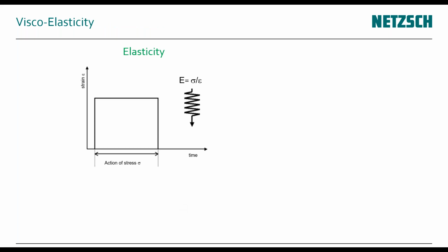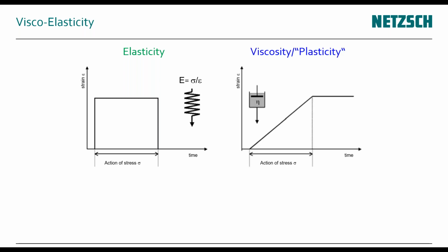So what is that viscoelasticity? We can think of a polymer being made up of elastic parts. So they're like spring-like parts you can see here on the right. What happens with the elastic part: you excite a sample, so you apply a stress upon your sample. And once you do that, there will be an instantaneous strain. It just stays like this. If you take away the stress after a while, the strain will just go back. So this is regularly the behavior of a model system like a spring. So you can think of your material containing some spring-like behavior.